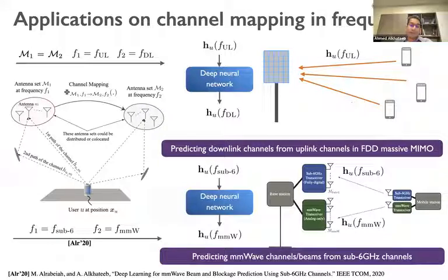In some cases, if we are designing these models for systems with hardware constraints, such as hybrid analog digital or analog beamforming architectures, we may need to look at complex valued neural networks, or even design some of the first layers in these neural networks to account for the hardware constraints. Otherwise, these networks may not even be deployable. So the approach would be to deploy part of this neural network in the phased array, or to treat the phased array or the hybrid analog digital architecture as part of your neural network. To do that, you need to model these first layers as complex valued neural networks, maybe with a unit modulus constraint, so it's even more constrained.